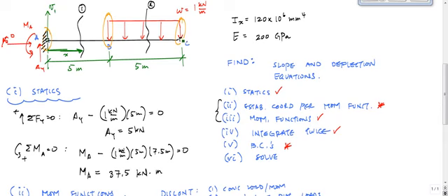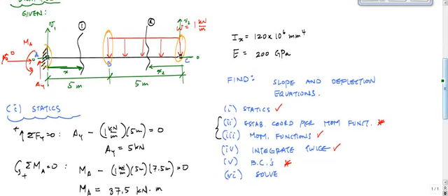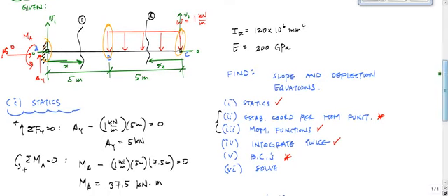And then for moment function 2, I'm going to define it going right to left with x2 going right to left here and V2 upwards, with 0 being over here. So this point right here is 0 deflection, V2 going upwards that way, x2 going right to left. All right, so that's important. How we choose the coordinate system really does affect your understanding of this method and eventually getting the correct result.